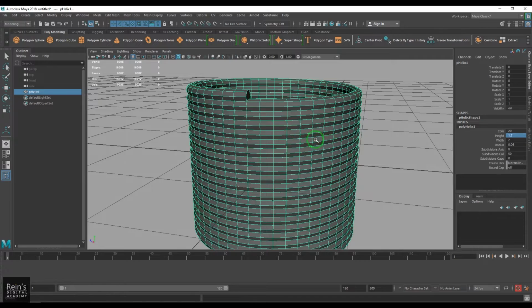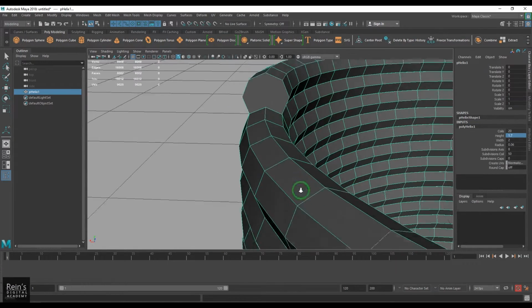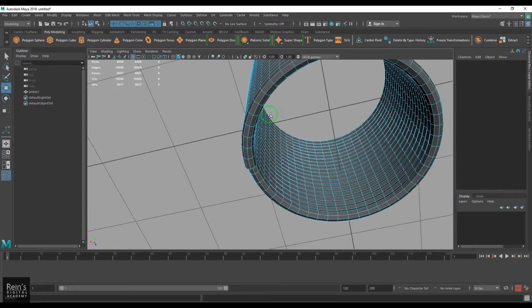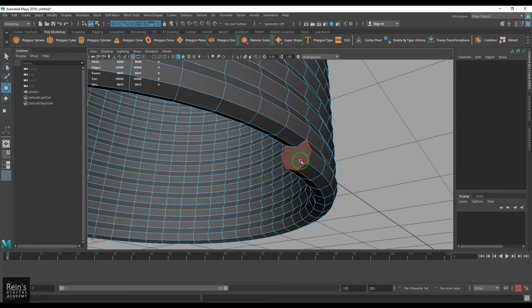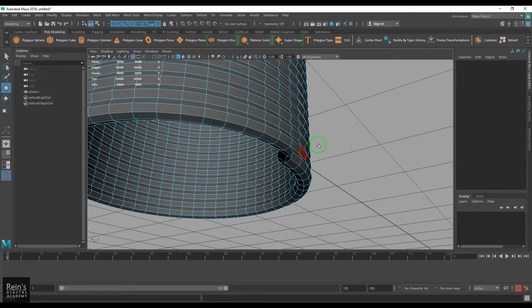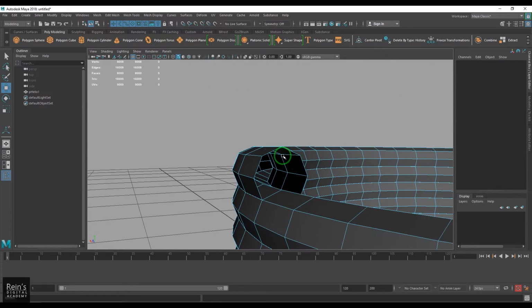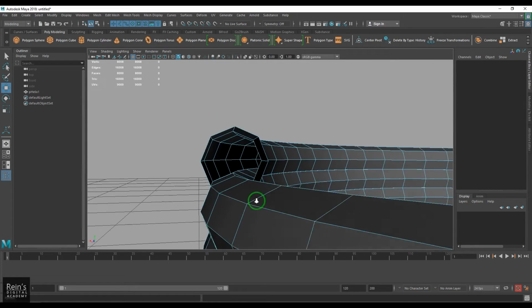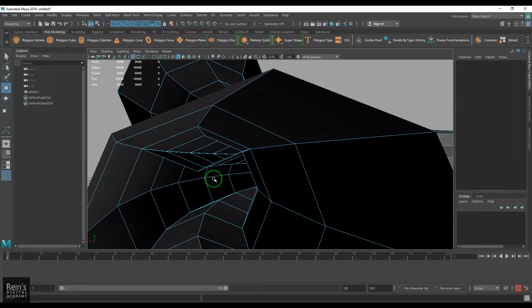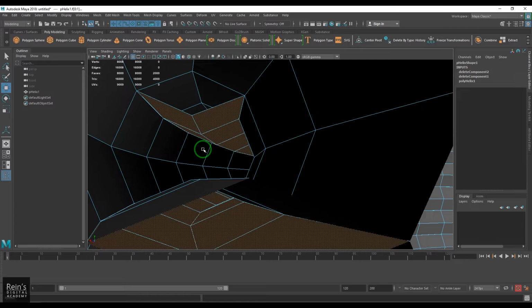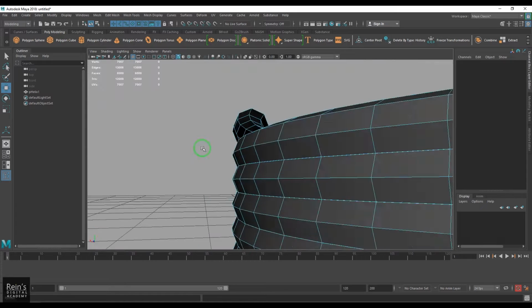So what I am going to do here is delete the cap here and a cap here, and what you should be able to see is the faces of this particular circle are inside. So I need to double click that line, hold control right click, convert selection to faces and delete them. That's gone.